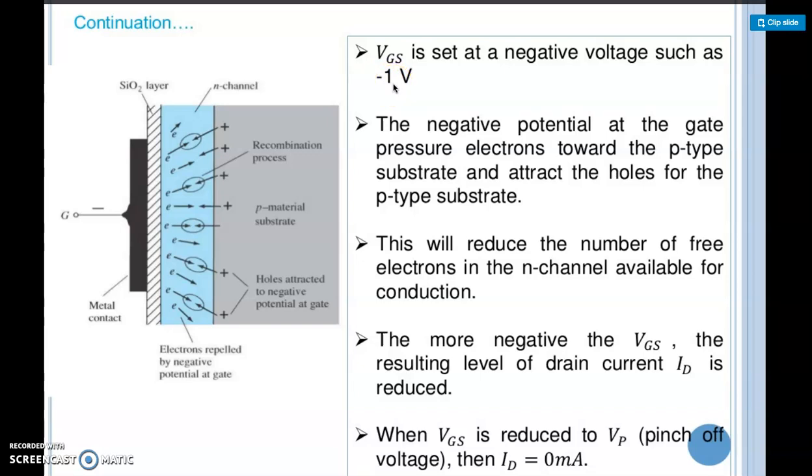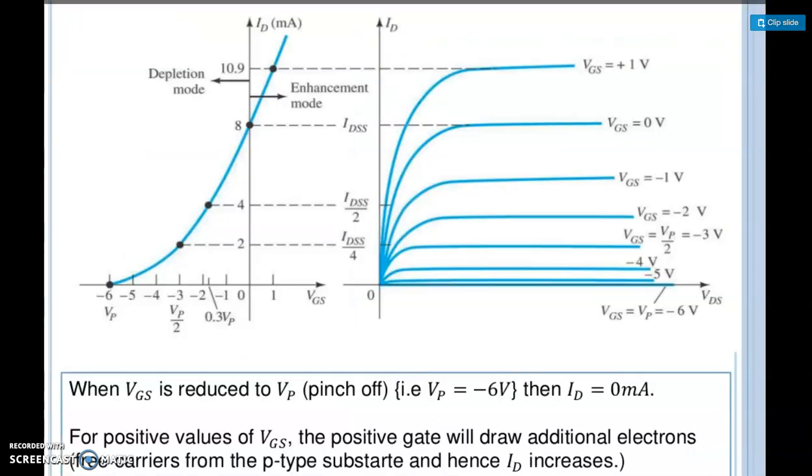So this is being shown by the characteristic curve, and this is a kind of drain characteristic as we have seen in JFET. The drain characteristic is plotted ID versus VDS. So first case is with VGS equal to 0. This is the characteristic plot similar to your JFET, and with VGS equal to minus 1 volt, like in JFET only, you are going to have one more curve with ID reduced.